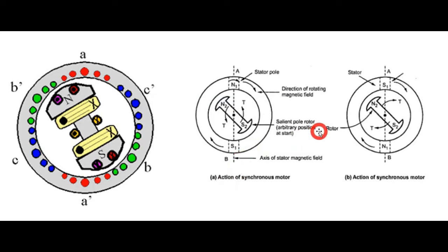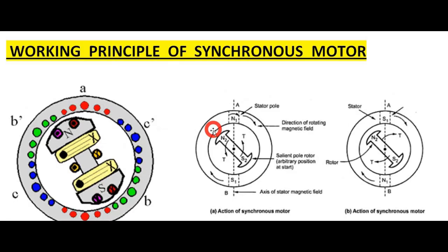Then, how to start a synchronous motor? As I said, the synchronous motor is not a self-starting motor. Then how can we start it? Suppose the rotor is rotated by some external means at a speed very near to the synchronous speed.